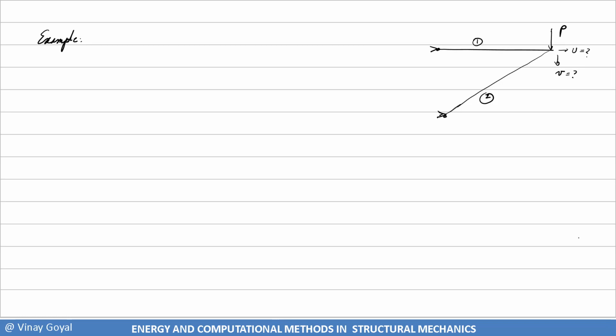And so the first thing that you need to do is calculate, so use the first Castigliano theorem. That's what we want to use in this example. So you calculate the strain energy first, which is the triple integral of 1/2. This is a truss system, so only axial load can be taken by this system.